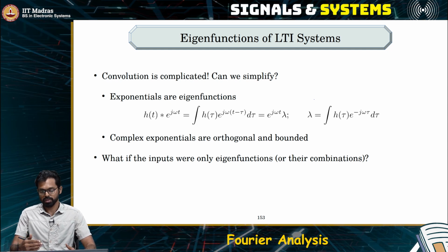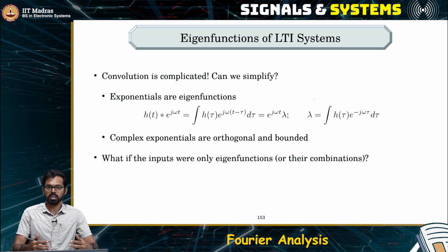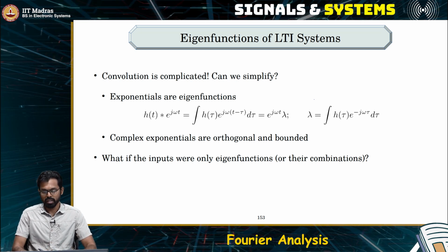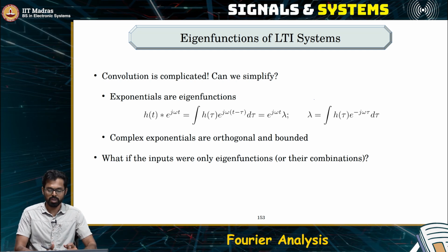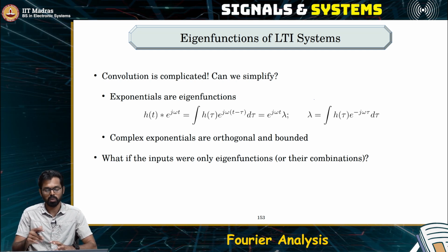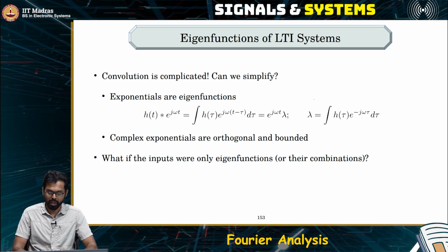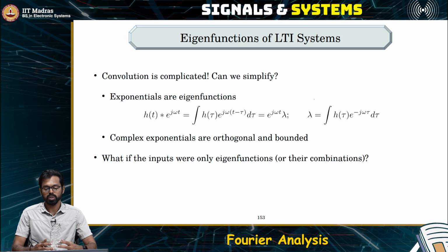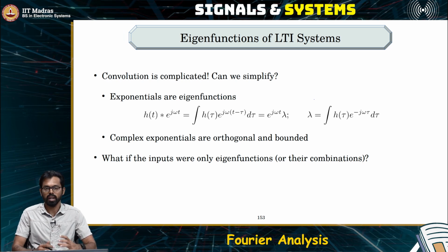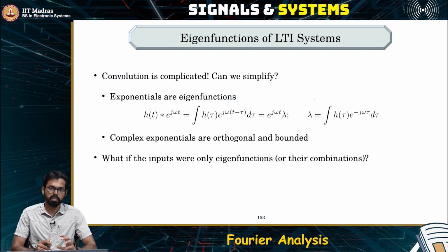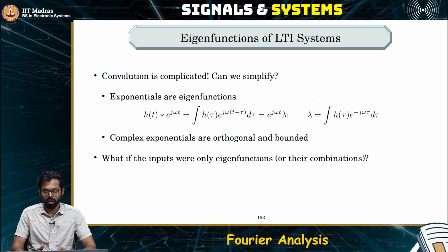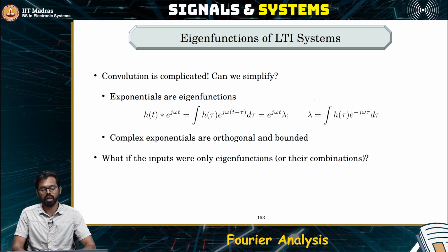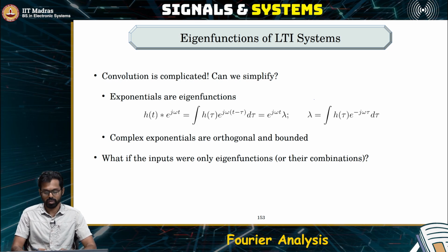It so turns out that Fourier analysis simplifies the computational complexity of convolution. If you have to convolve two signals, even computers take more time to do the convolution than to simply take the Fourier transform and implement the convolution using Fourier transforms. So we are using a tool known as Fourier analysis to analyze these signals and represent them in a different form, where it becomes easier for us to identify what the input and output of a system are.